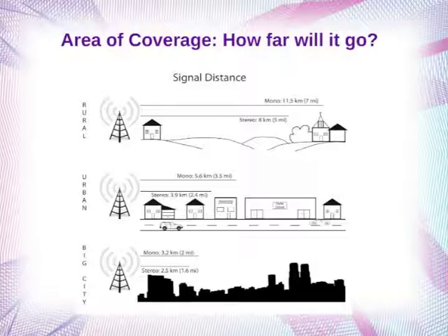The thing is, the newer radios have good filtering, and so the second and third adjacent interference isn't as much of an issue as it used to be. And like I said, most of us are going to be in areas where third and second adjacent quote-unquote interference is a reality, so we're just going to have to deal with it. That's why I didn't put it in the frequency summary page.